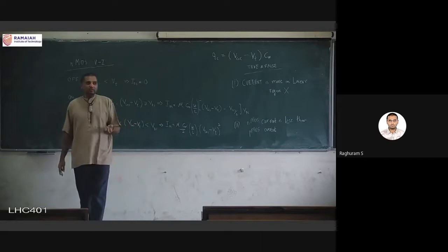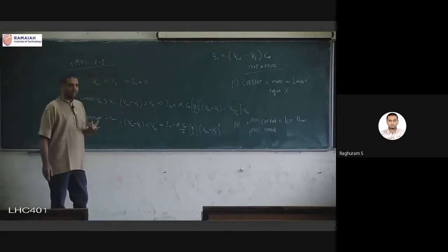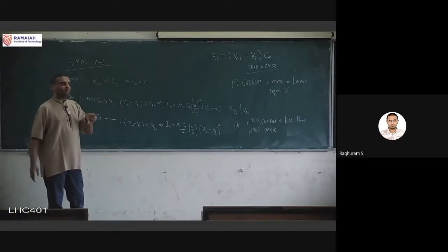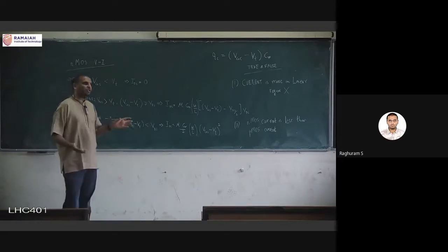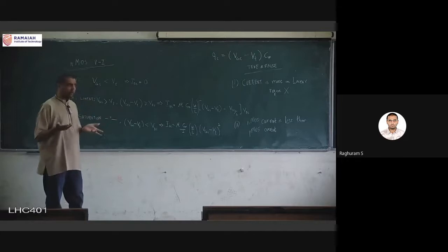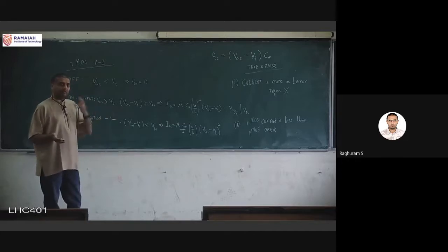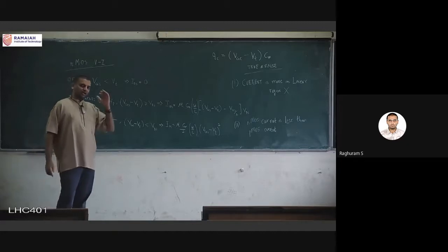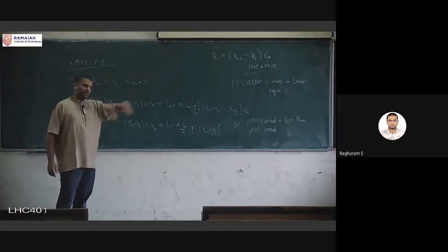Mu, we said, is a physical parameter, definitely yes. But now that we are talking about NMOS versus PMOS, the mobility is of the charge carriers. And since the charge carriers are different, the mobility is also going to be different. And this is not easy to guess, of course. Electrons and holes are identical except for the opposite polarity. And also the mobility for electrons is much higher, because electrons, if I apply a voltage, they will move.